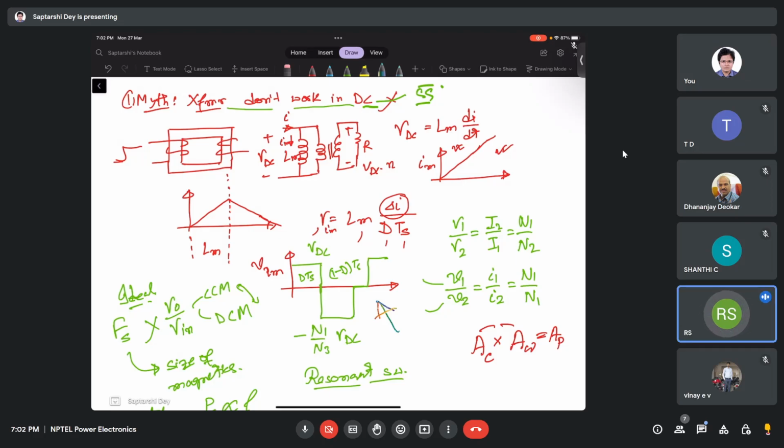So you are saying that across a magnetizing inductance, pure DC is given. Yes, if you do that, then something will fail after a very short time, either the supply or the transformer. And also the circuit will never come into steady state. It will always be in transient.